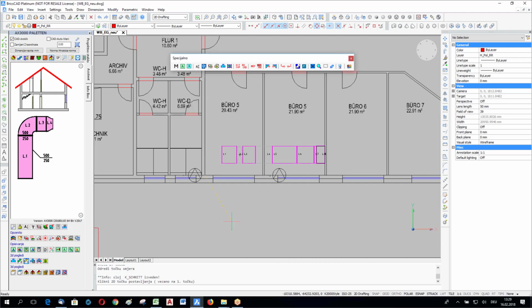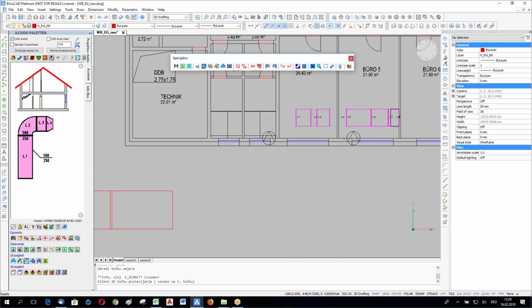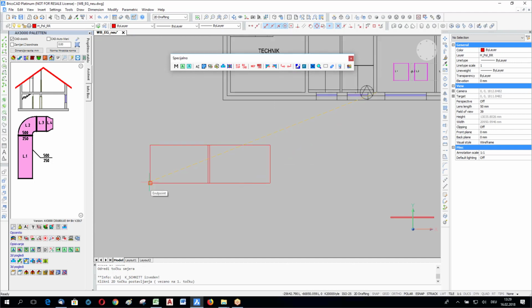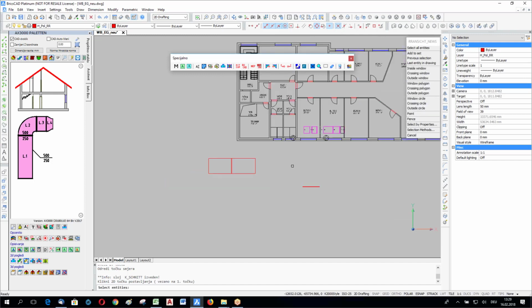The software is drawing 2 symbols. They are saved as a block inside the drawing. And I want to have the section here. This must be the same point that I have selected in the plan view, because this is used to move the ducts to the left and to the right, and this should be on the reference height you have inserted in the dialog before. So if I insert 0 and this is the level of 0, I have to select this point. And now there's a question, which duct or elements do you want to see, and then I can select my elements that should be visualized inside this section.